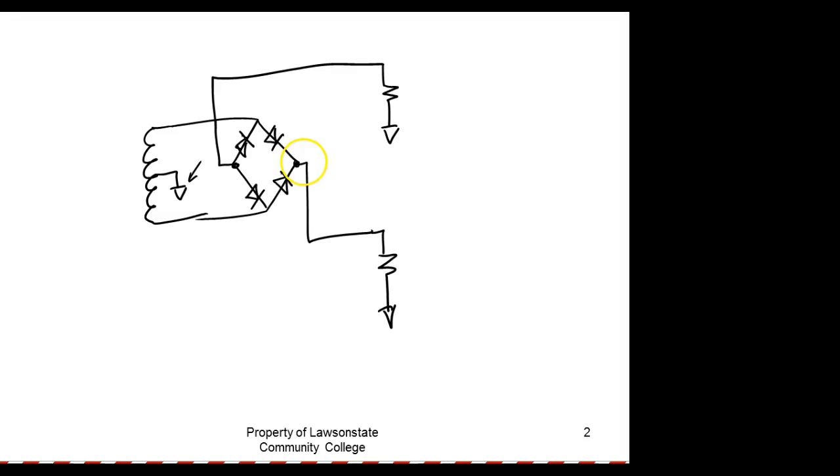If you look at this one, the anodes are pointing toward the source. If you look at this one, the cathodes are pointing toward the source. So this would be negative positive, this would be positive negative. So what you've got is it's using a bridge rectifier, but it's using it for a full wave center tap. This is what the trainer uses. That's what they use inside this thing right here. I guarantee this is what they probably use in your stereo out there.